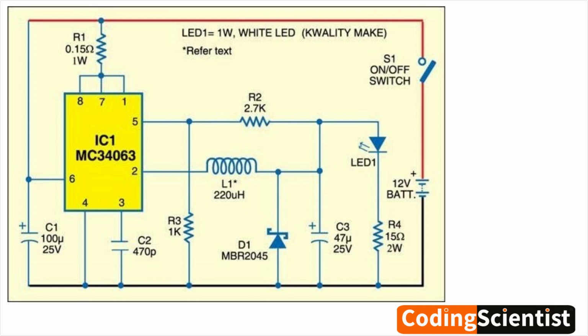Voltage regulation. The MC34063 constantly monitors the output voltage and adjusts the duty cycle, the ratio of on-time to off-time, of the transistor to maintain the desired output voltage.